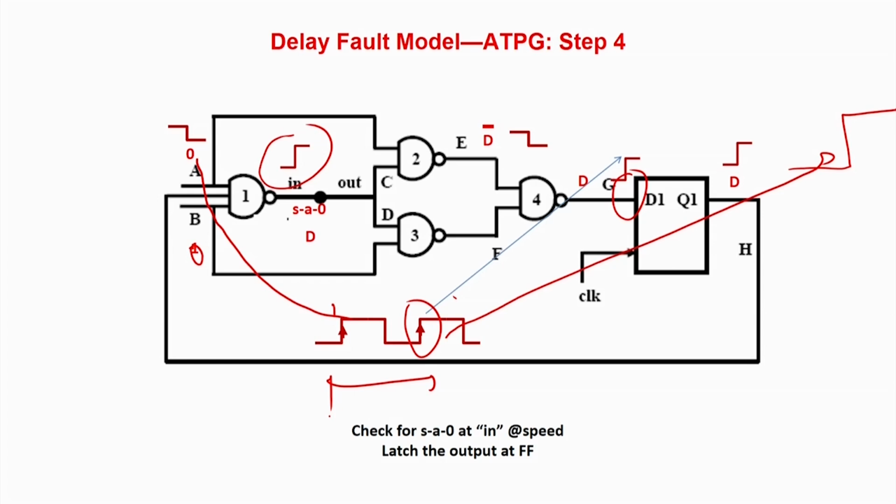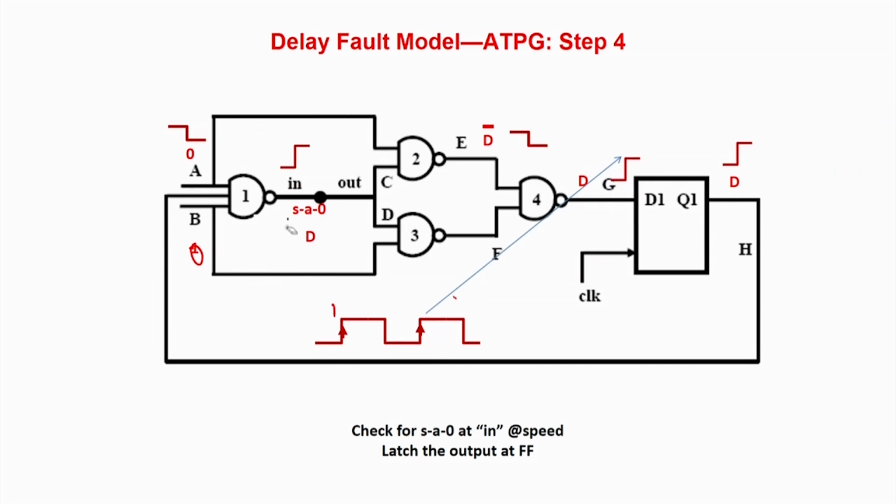So, what is the delay fault model? It is very similar to testing of a stuck fault model or a bridging fault model, in which, in the fault path, you have to give a sensitization. Sensitization is nothing but, for delay to rise, you first apply a 0, and in the next part you make it a 1. But that 1 has to be applied in a very fast manner, at the level of speed, and then you have to latch the value at the flip flop also at the same speed.